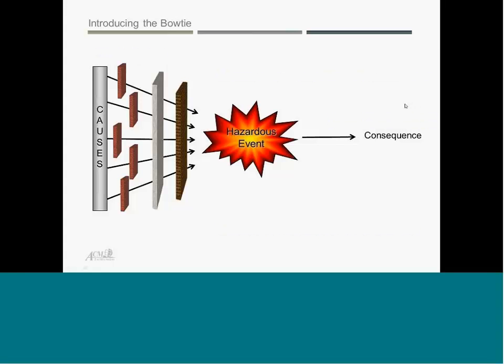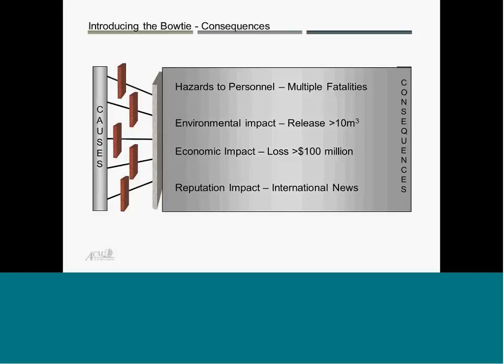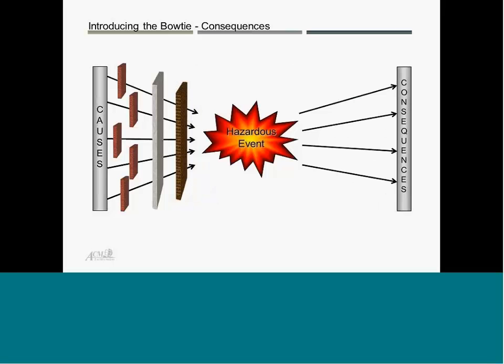I mentioned that this was a traditional LOPA. You're going to be looking at just a single consequence at a time, but is there any real reason to only look at one consequence? And the answer is no. SafeGuard Profiler allows you to look at multiple consequences of the same hazardous event at the same time. So in our case, in the Hazop, we identified 4 different consequences, all coming from the same overpressure. Those can all be analyzed at once.